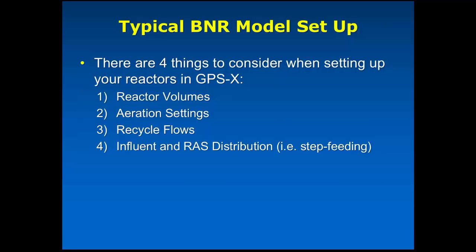Recycle flows, and by that I'm mostly speaking of the internal mixed liquor recycle, so flows that take things from, you know, an aerated zone back to an anoxic zone or an anaerobic area. Those types of things, I'll show you where you set those up.